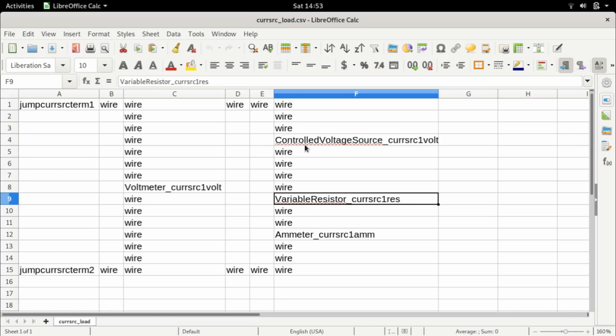What is important? Now we have a working simulation where we have replaced our variable resistance and variable inductance by a controlled current source, which again is represented by a controlled voltage source in series with a variable resistance. So how are we going to use this to model any variable load, and moreover going further an electrical machine? That's going to come in the next few lectures.